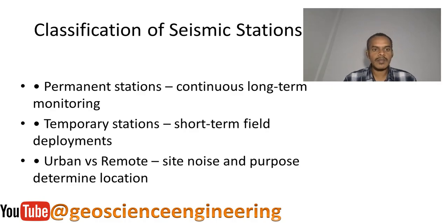And then we have the broadband seismometers, which capture a wide range of frequencies and are used for regional and global monitoring. And there are strong motion accelerometers, which come with both the seismometer and accelerometer together, and these are used to record large near-field ground motion that occurs during strong earthquakes. This is mostly used for engineering studies.